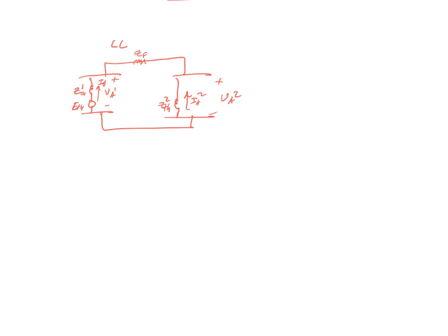So at this point, even though they're in parallel, they're actually just two of them, so they're technically in series. So we're going to solve for IA1 as equal to E Thevenin divided by Z Thevenin 1 plus Z Thevenin 2. Now we can solve for IA2, which is in the opposite direction of IA1 but the same value, so that is equal to the negative of IA1. And we know that IA0 has to equal 0 because there is no ground fault current, so there wouldn't be any current flow as a result of that.